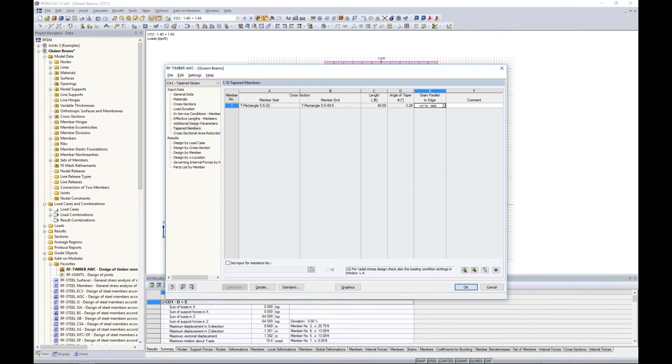Going back to RFEM, that's the default. Now there are cases such as if a beam is in uplift, for example, or maybe a cantilever, or anything of the sort where you can use your engineering judgment to change this to something otherwise.